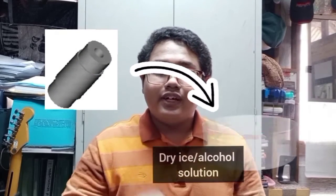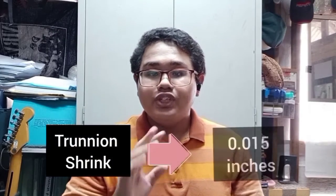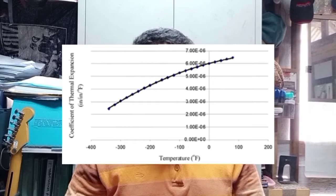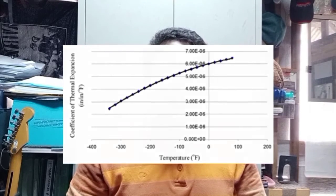So, according to this calculation, immersing the steel trunnion in a dry ice alcohol combination results in the necessary shrinkage of 0.015 inches, despite his prediction of 0.01504 inches. However, as shown in this figure, the thermal expansion coefficient of steel declines with temperature and is not